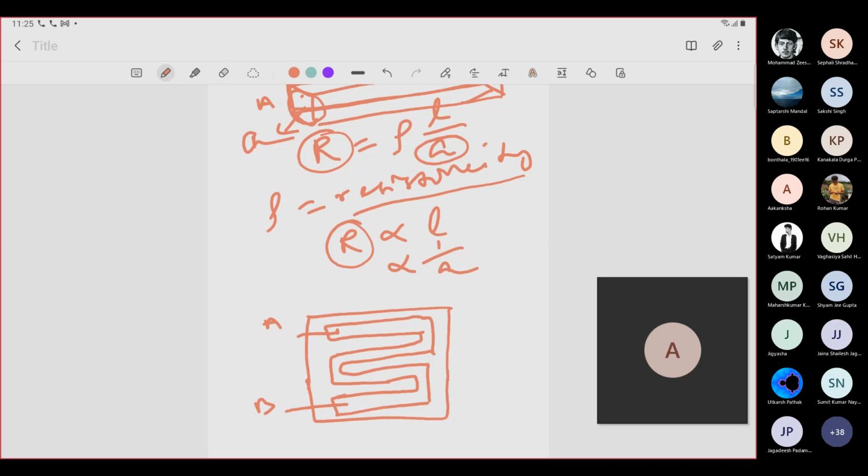If that is not sufficient, you can have a stack of these resistances connected to each other. You put the resistance material, put a silicon dioxide layer above that, then put the resistor material again above that and make the connection between these two layers.